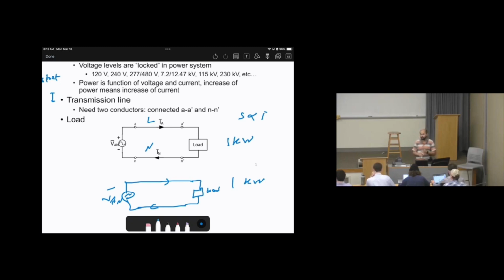The other thing is the overall cost. You are connecting the power lines based on the infrastructure of the towers, even the weight of the wires. If you increase the thickness, this will increase the weight and affect the mechanical structure of the towers. It can be very expensive because we need to modify all of the power lines and utility poles so they can handle that larger thickness.